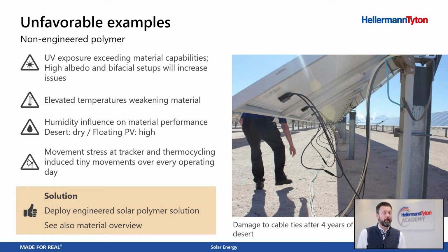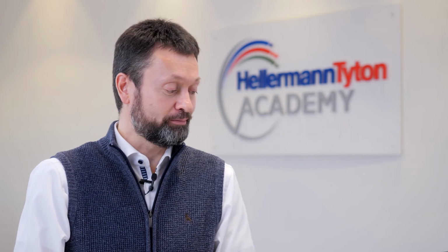Always take care that elevated temperatures are also weakening plastic materials. So choose the right material to overcome this kind of thing. Also, humidity is highly underestimated. Very dry areas and also very humid areas are impacting the properties of the material. There's another webinar where I'm going to talk about the material properties and the influence on that one.